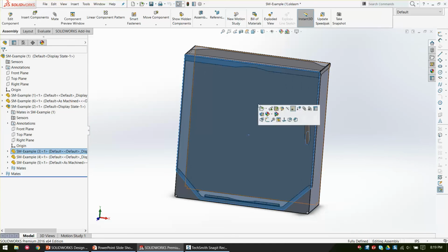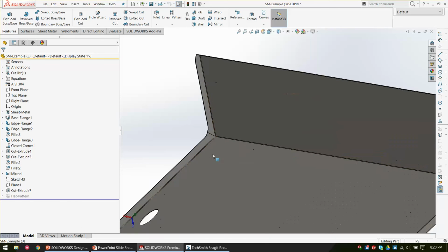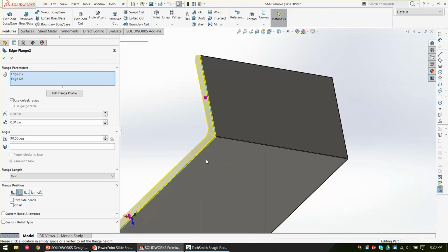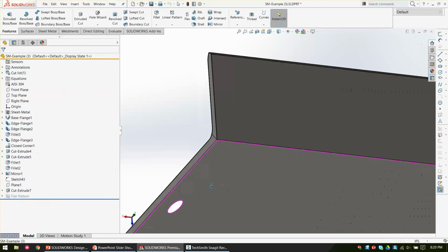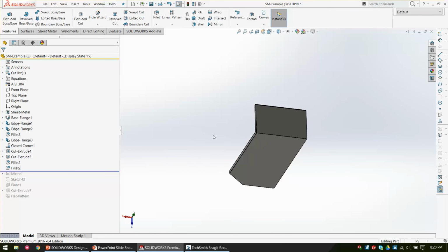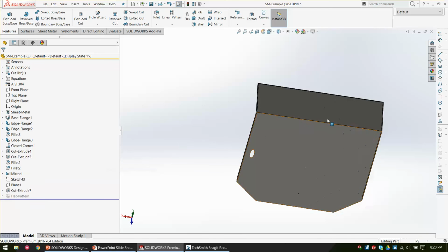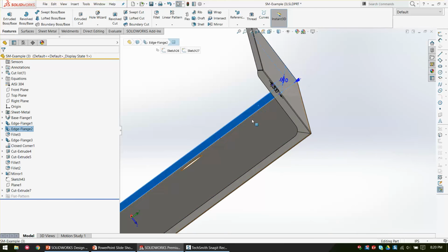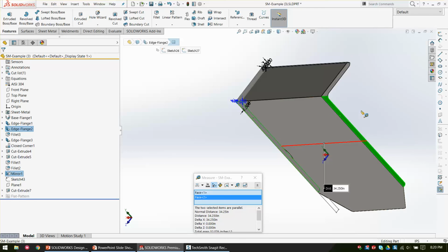So on my lid, I wanted to add the material thickness on my edge flanges outside my material. So my driving dimension is an inside dimension. And you can see here too, I also used a mirror because there is certain geometry I didn't want to take the time to duplicate, so I just drew half of it, then mirrored it over. But if I measure the inside of these two lips, I get 34.25.